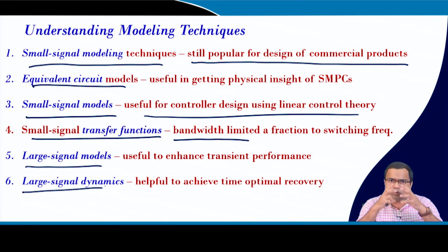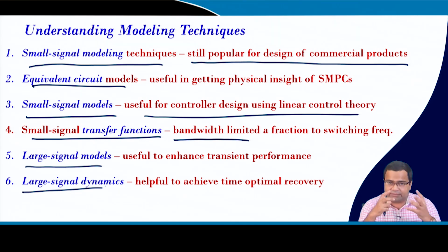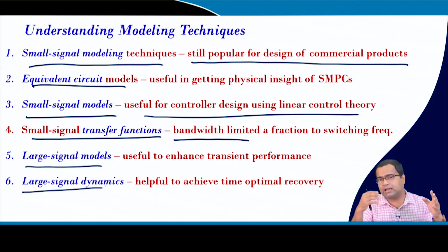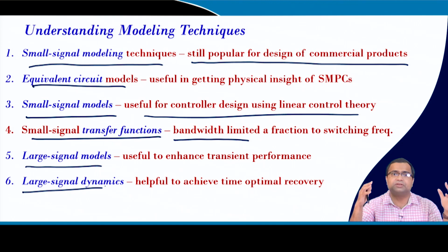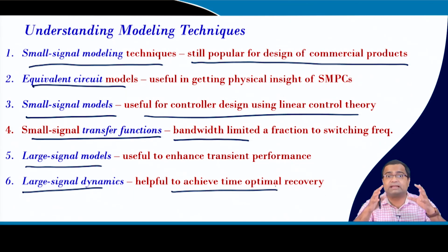So, your thermal overhead will come down, and in future you will find products coming without any heat sink, because in fact the wide band gap devices themselves are very efficient, and if you can make the controller also very effective, the power converter can be very efficient. So, you can reduce the heat sink size significantly, and at the same time you can also decrease the output capacitor.